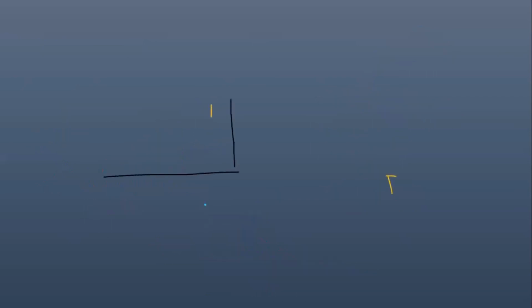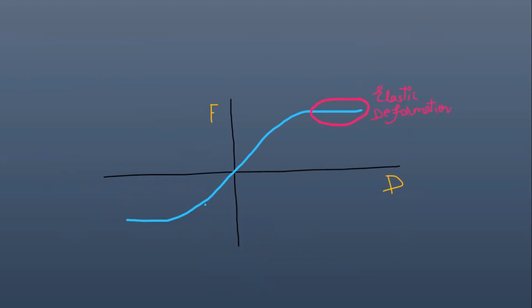If you plot a real spring's stretch length versus its restoring force, it would most likely have a shape similar to this. When you stretch it too far, eventually the material will start deforming. If you compress it too far, the coil will start bunching up and physical impact occurs. We select somewhere in between, what can be considered the operating region of the spring, where there will be a nice, nearly linear relationship between the force and the distance, when you are selecting a spring for your design.